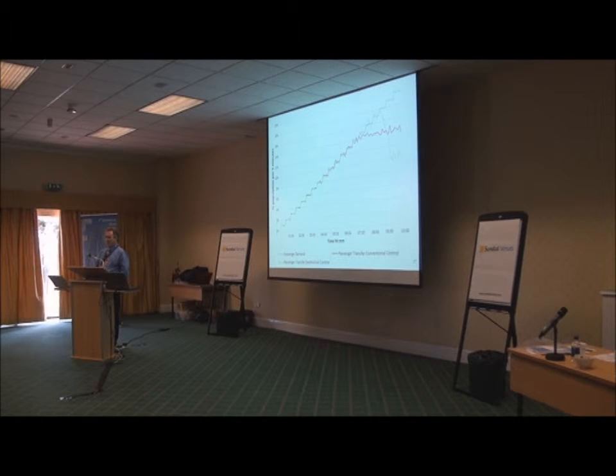Me and Elizabeth counting people in buildings. Yeah, that's actually the number of people that actually get into the lift, and that's one of the graphs that we produce. And you can see as the demand goes up, and you remember my handling capacity was 14%, if you watch the red line, it separates from the demand curve at 14%. Yeah, and that red line shows you what the handling capacity is, and this is a really good way of working out what the handling capacity is using simulation. Quick one shot, you know the answer. So I find that really interesting.